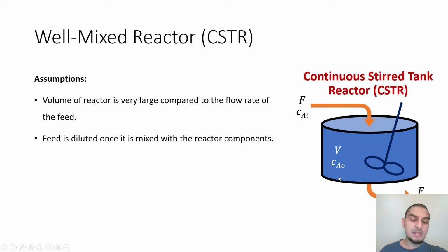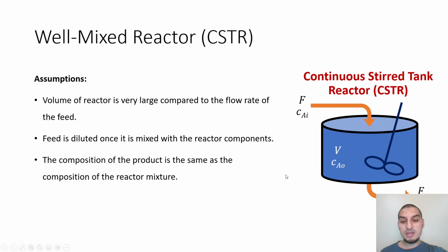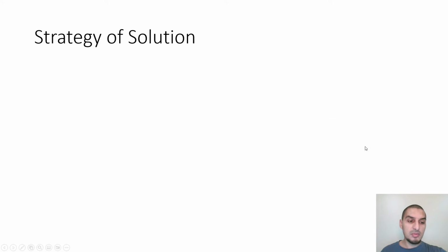So in any term related to the process taking place inside the reactor, I will use the concentration of the product. This is the important part. This has to do with the concentration of the liquid that I use as a boundary condition in the biofilm, and this will also be valid for the reaction term that I am going to use for the KCA. So for the surface, the CA is CA out, it's not CA in. I'm not going to use CA in anything related to mass transfer inside the reactor. So this is one important point to keep in mind.